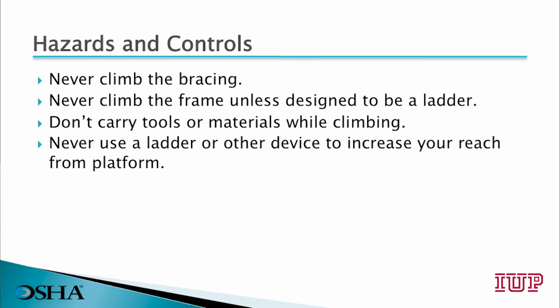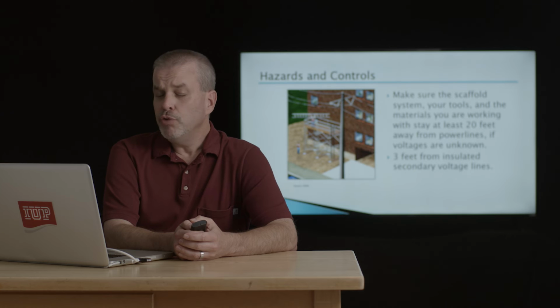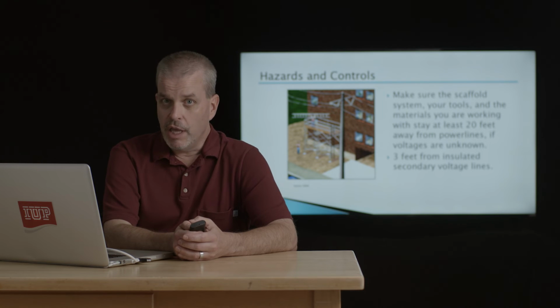Never climb the cross bracing on a scaffold. Never climb the frame unless that frame was specifically designed to be a ladder. Never carry tools or materials while climbing. Never use a ladder or another device to increase your reach from a platform. Make sure the scaffold system, your tools, and the materials you're working with stay at least 20 feet away from power lines if the voltages are unknown. Make sure you maintain at least 3 feet from insulated secondary voltage lines.